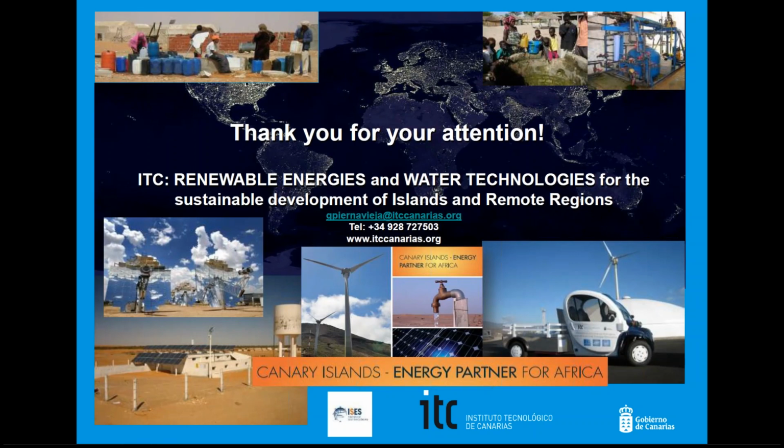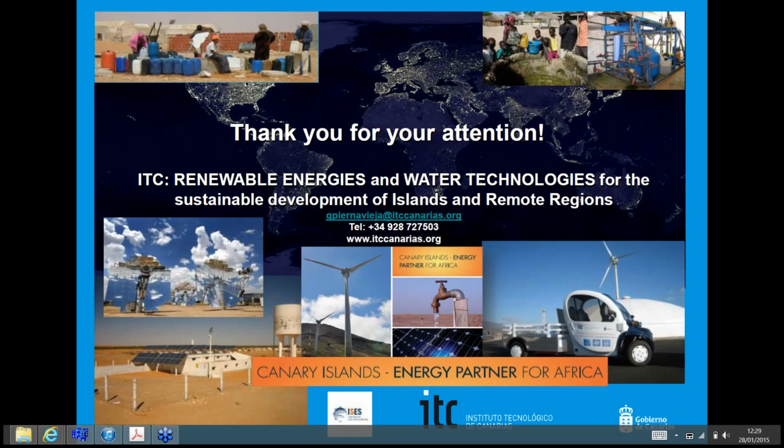So we have been working in PVRO either standalone or grid connected. If you are operating PVRO in an off-grid, very remote area, we are for the time being recommending coupling with batteries, so that you have a stable supply, because reverse osmosis is sensitive to fluctuations in energy. So we are advising to have batteries in these systems.